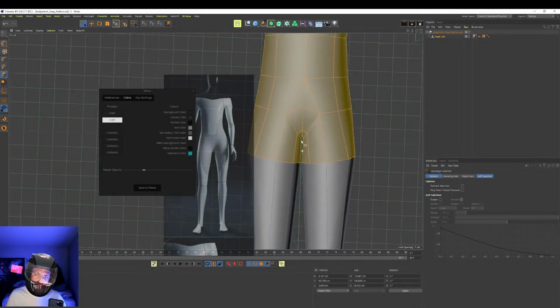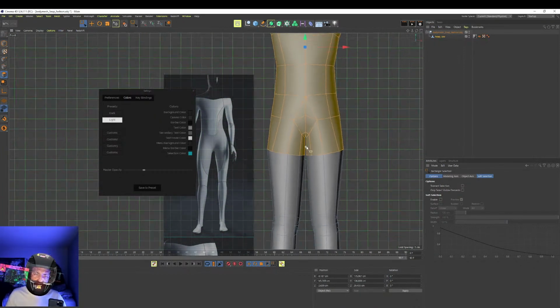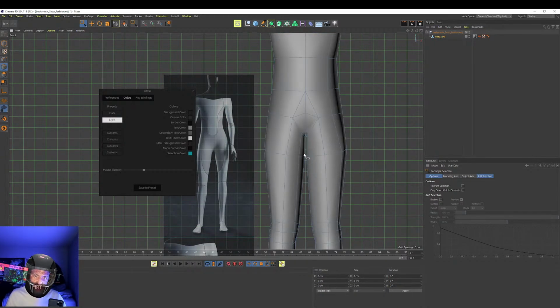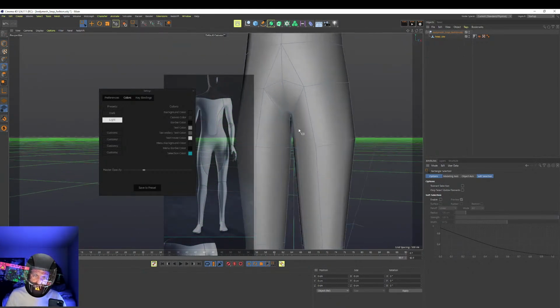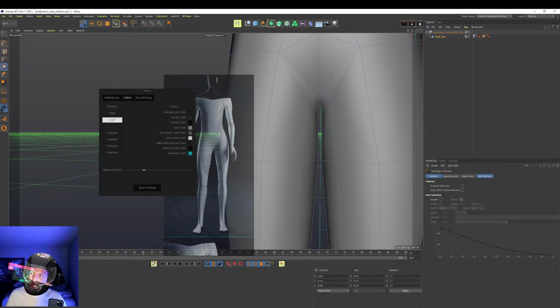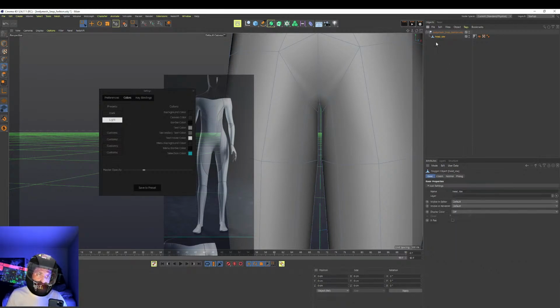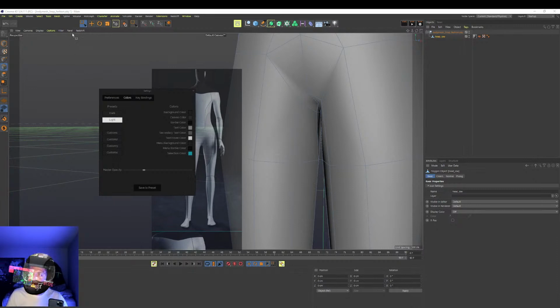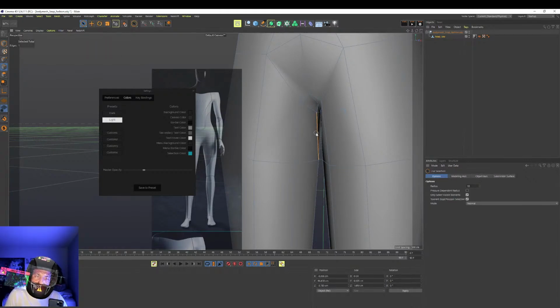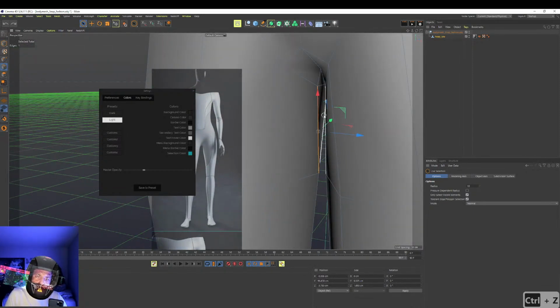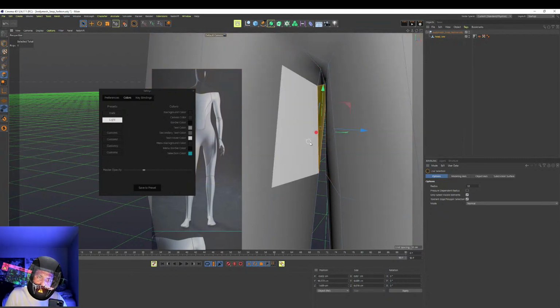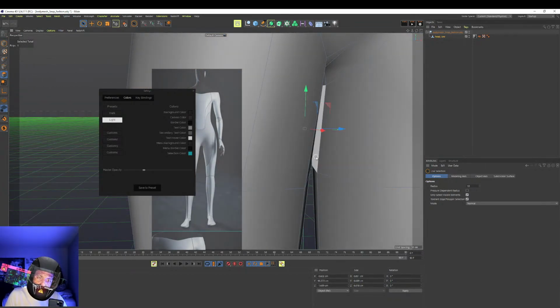If there's a little bit of space between the legs, between the inner thighs, we can actually push the model and not have the leg binding get mixed up. So I'm going to grab the inner line on the leg geometry here. I go to polygon selection, go to edge detection, and just grab a live edge. I'm just going to grab these two edges. Actually, I guess we just grab the triangular face there. So we'll grab the triangle and grab this triangle.